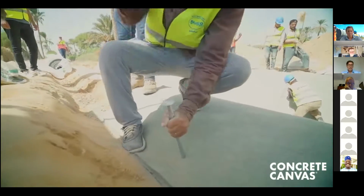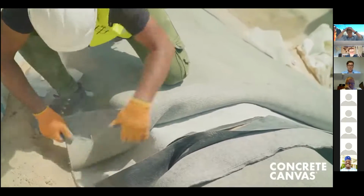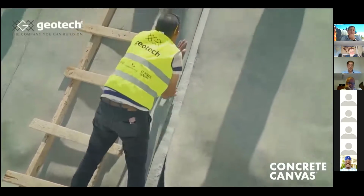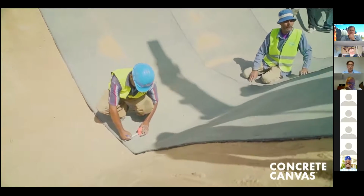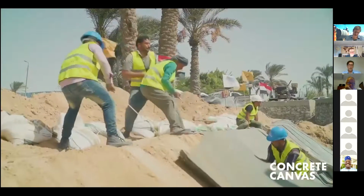The LLDPE membrane backing is very smooth and has a low coefficient of friction. In order to stop the slipping of CCX barrier into the canal during the alignment and jointing exercise, a temporary peg was installed within the anchor trench midway between the overlaps. Sandbags were also used as ballast to ensure close conformity to the underlying profile.